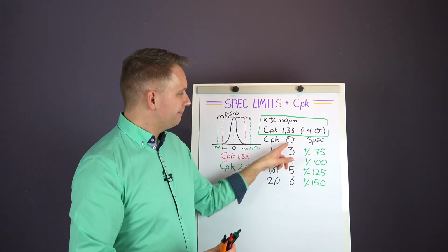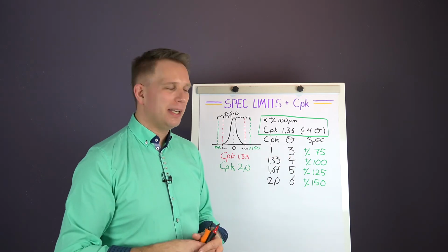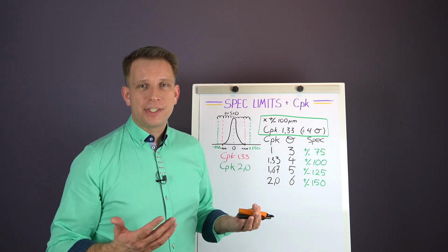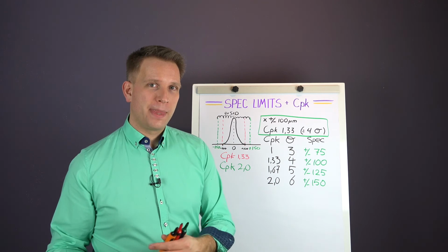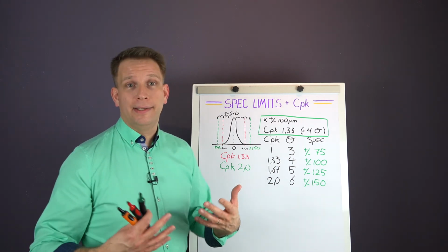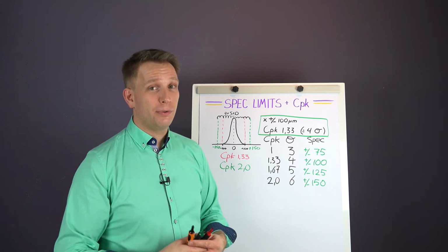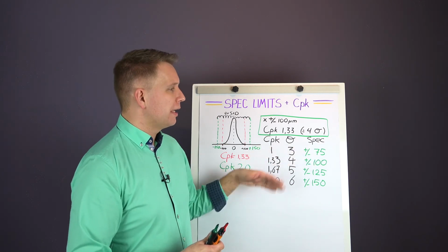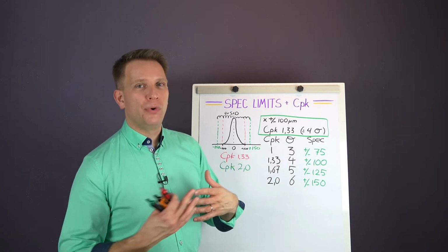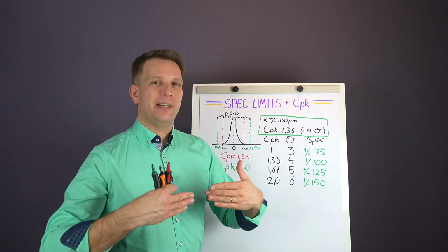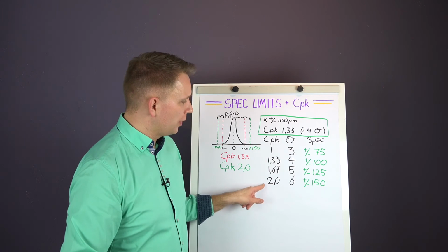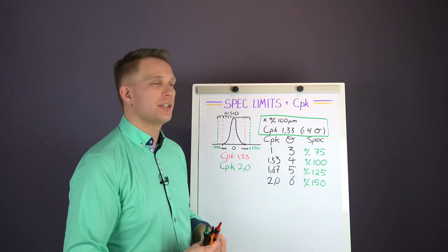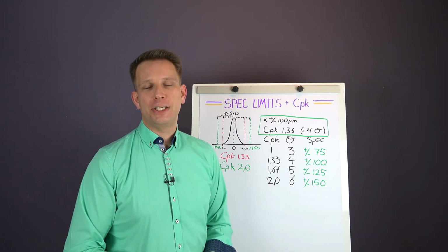At that moment, you know that, okay, CPK 1, 3 sigma levels, that will give us a mistake, a problem, at least a couple times every 1,000 parts. And if we're in a high volume manufacturing organization, several times every 1,000 parts will happen, maybe daily. So that will give us a relatively low reliability. So when we are designing for Six Sigma, we need to make sure that we can handle the tolerance that fits with 6 sigma of variation observed in each part.